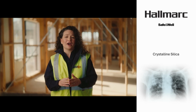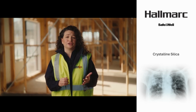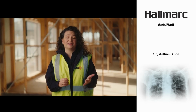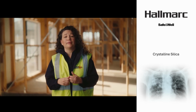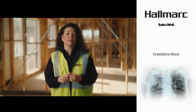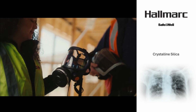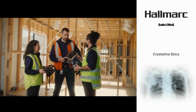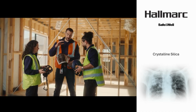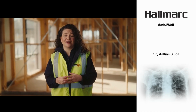Respirators are commonly required in two types of situations: to further reduce exposure when a higher level of control isn't enough, or if a respirator is the only option. But often a combination of risk controls may need to be used. Respirators work by either filtering contaminated air or supplying clean air, so that a person's exposure to the contaminant is reduced. Always choose a respirator and filter that is suitable for the task.